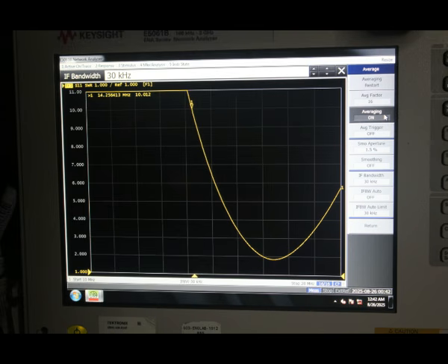Instead of that coax being connected, we connect this Keysight ENA, and then we can adjust the load match tuner for any SWR into the transmission line at the antenna that we care to see. In this case, I'm going to first do a measurement with it at a 1-to-1 SWR to be sure everything's calibrated, and then I'm going to move the resonance of this system up out of the 20-meter band until I get a 10-to-1 standing wave ratio on the ENA.